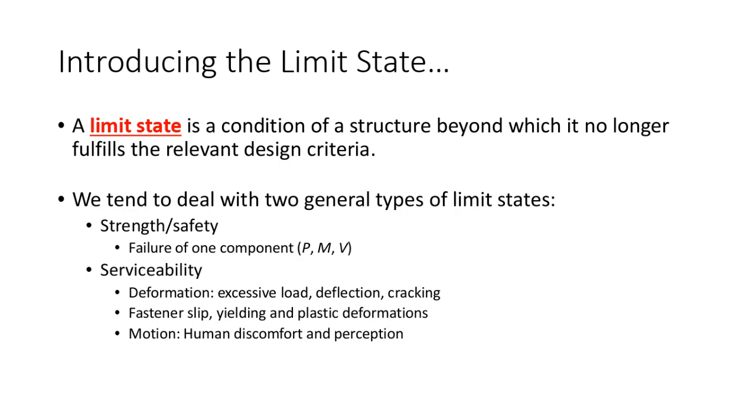And so we call those serviceability limit states. Serviceability limit states are ones that are not related to failure, but more about day-to-day performance of the structure. So if you have a structure that vibrates too much, or deflects too much, it might not fail, but it's not doing what we want it to do.